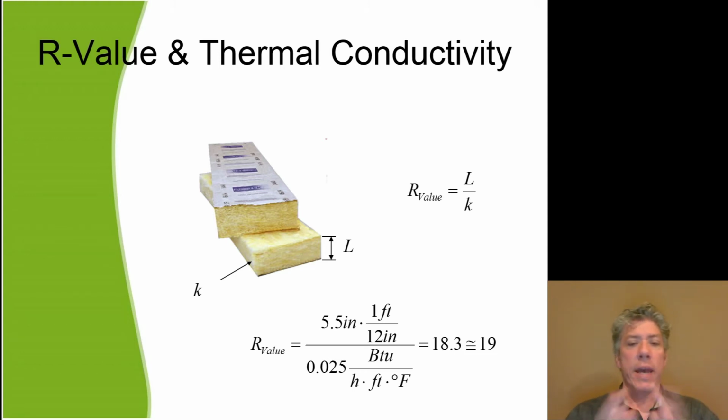Well, actually, the bat itself has to expand in the wall cavity. If it doesn't, if it's compressed, then because the glass fibers are more thermally conductive, it'll actually conduct more heat, or heat at a higher rate, I should say, than the R11 insulation would. So it's very important that these bats of insulation expand out properly. You don't want to stuff a wall cavity with insulation thinking that you are enhancing resistance to heat transfer. As a matter of fact, that's the way that these things are specified, right, is with their R value.